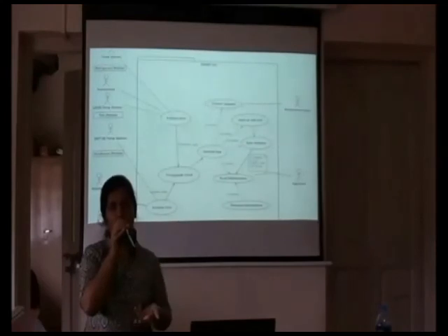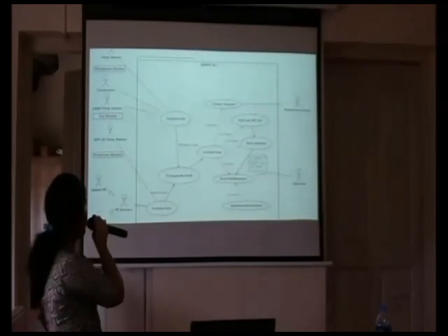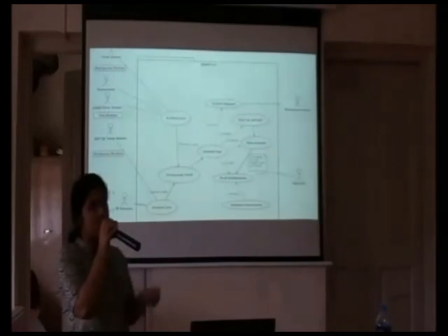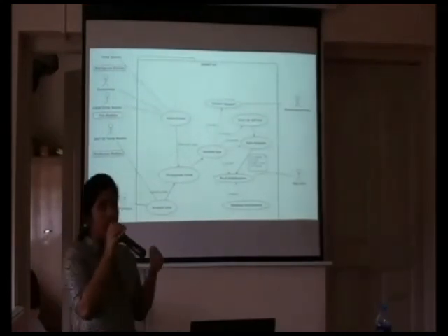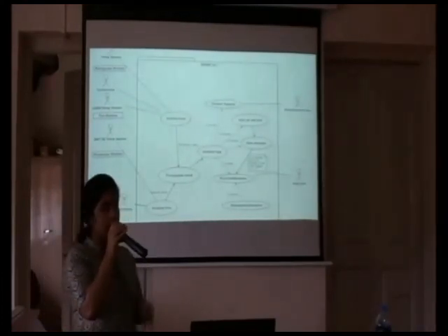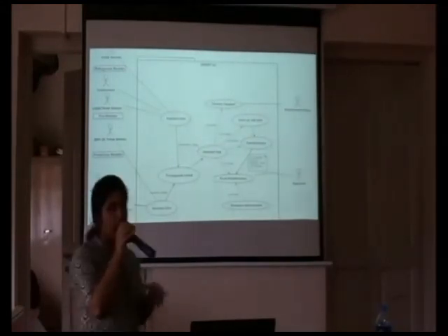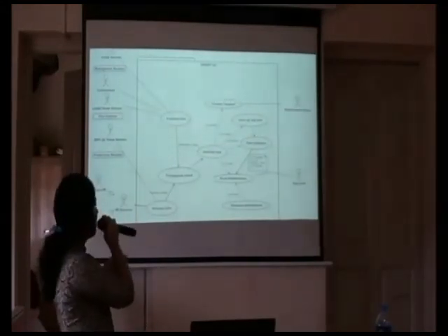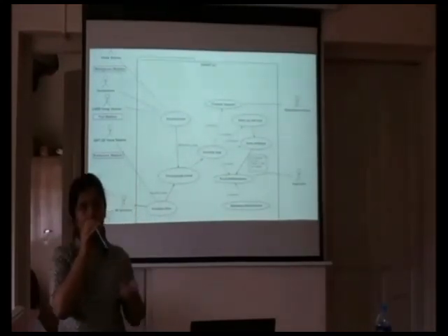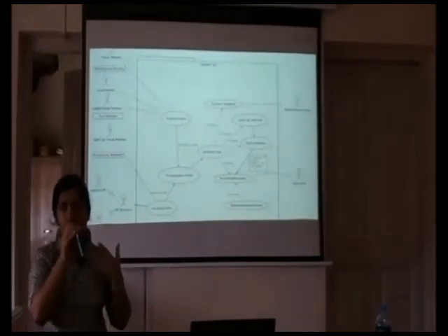The next comes the fan module. The two faults which can occur in a fan are motor complaint or capacitor complaint. We use a tachometer and an LM35 temperature sensor. The tachometer is used to measure the RPM. If the RPM is less than the predefined value, then it indicates that there is some fault with the motor and it needs to be repaired. Then the LM35 temperature sensor is placed on the motor, and if its reading is greater than 40 degrees Celsius, it indicates that it is a capacitor complaint and it needs to be changed.